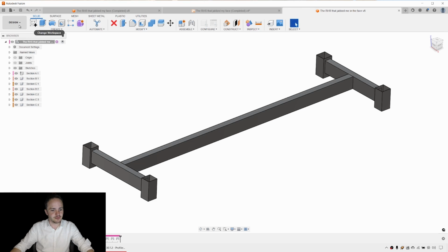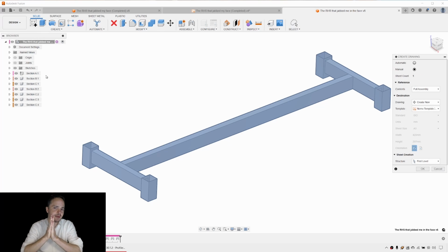All right, so to make a drawing, we'll come along to design and we'll come down to drawings and we'll say from design. And what we want to do is make a single drawing with many sheets. Well, we're just going to do two because we're lazy, but the first sheet will be the assembly and the parts list and maybe show a weld or two. And the next sheet will be one of the rectangular hollow sections in detail.